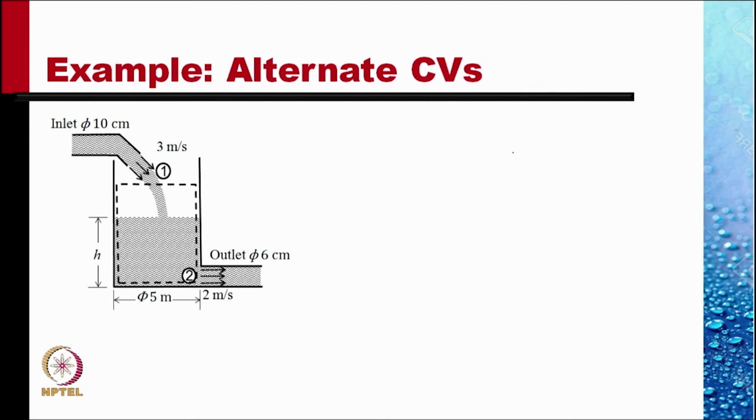The area would now increase to the area of the pipe divided by cosine 45 degrees. But when we find the flow, only the vertical component of velocity would contribute to flow across that area, and the vertical component of velocity would be v times cosine 45 degrees. So the product of the velocity and area would still be the same, VA. So we should get the same result.